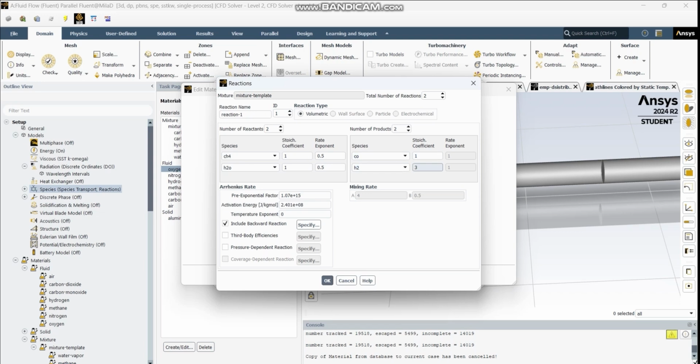This reaction drives the hydrogen production and requires a significant heat input, which is why the inlet temperature was set high. And I'm gonna show that. Pay attention to the Arrhenius rate, and this value should be used. Because the reaction is reversible and not irreversible, the conversion plays an important role because all the reactant